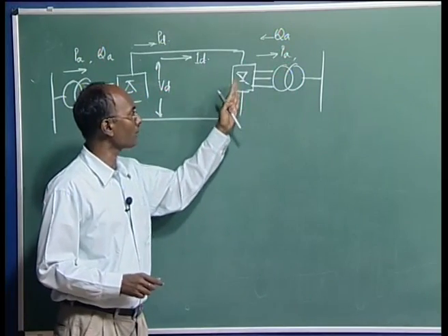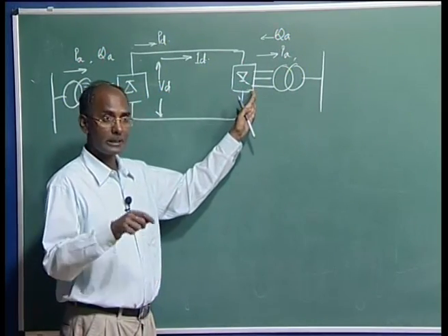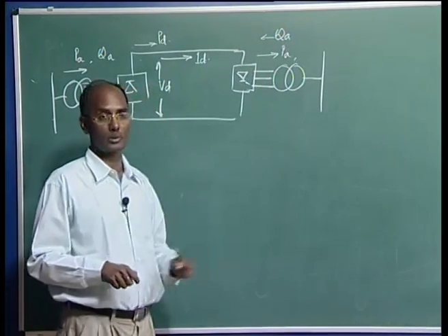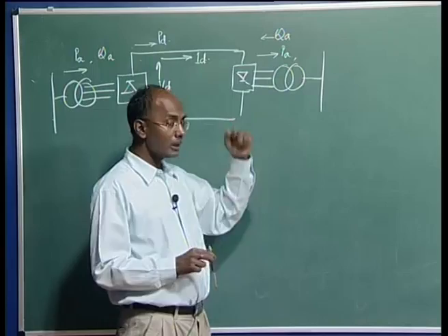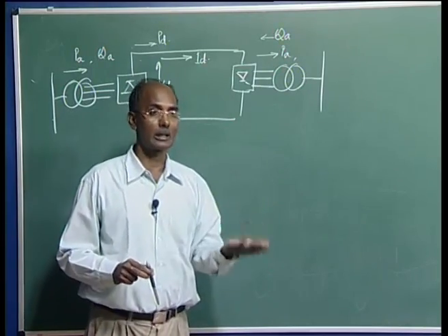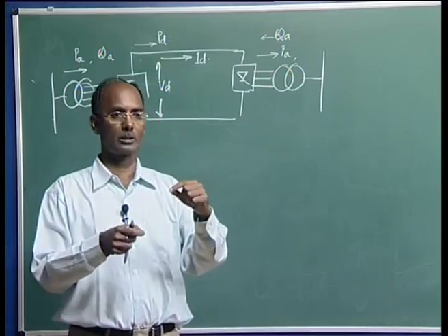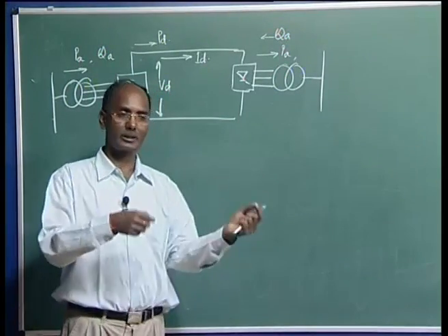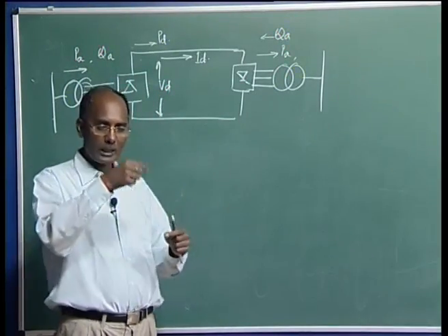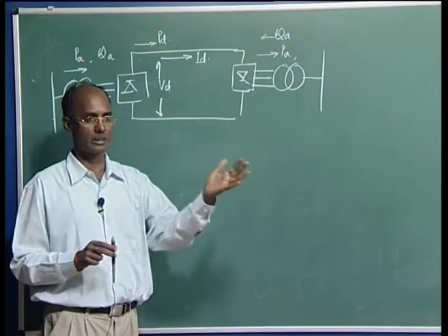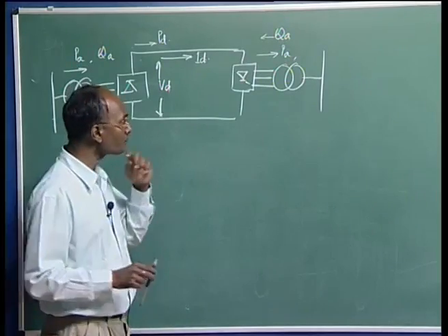Once we go for the design of the filter, we will see we are going to use some of the filters to eliminate or mitigate the harmonics so that they should not enter this side, meaning we provide the minimum impedance to ground. At the fundamental component it provides reactive power, meaning it works as an effective capacitor, although it is made of inductor and capacitor together, so we can have either tuned filters or band pass filters. We will see the detailed filter design later on.